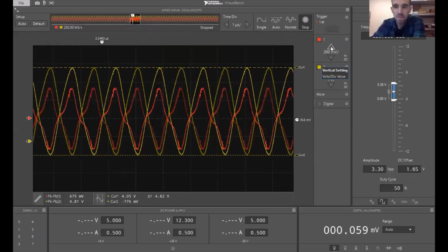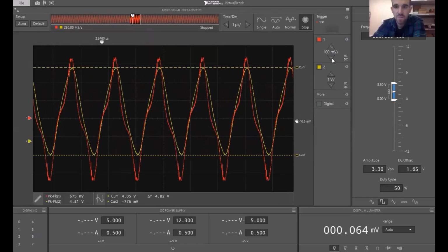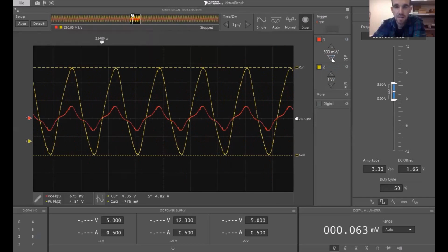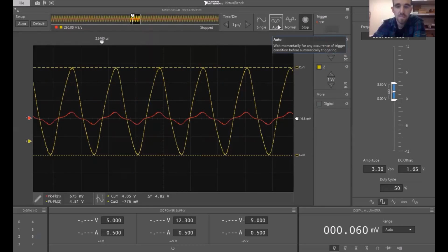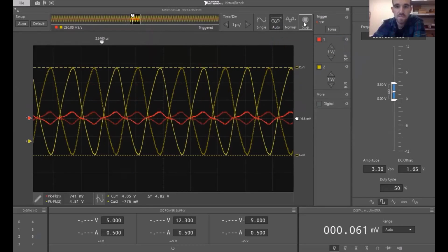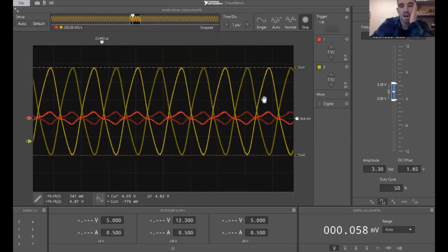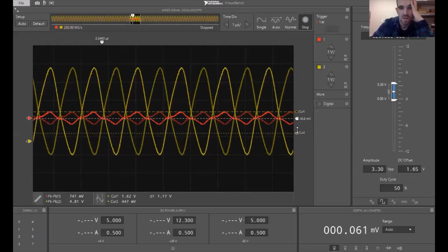So from there, I then want to measure the eye height of line 2. I take my cursor, make sure that your voltage divisions are the same, and then measure the top of this with the bottom of this.